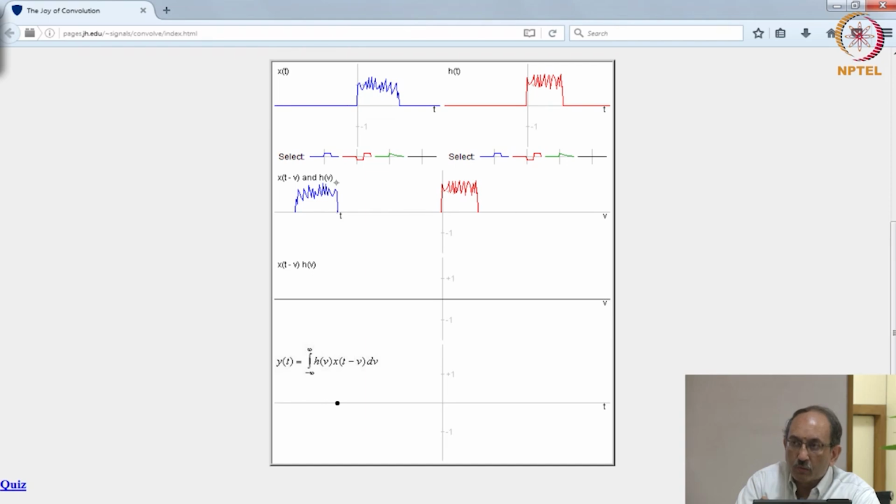So, now what I am going to do is, now I am going to convolve them. If these were two clean pulses, you would expect a triangular shape. Now, let us see what happens here. All right. The final result is still not too different from a triangle because all these variations have been smoothed out. So, this kind of nicely illustrates the fact that when you integrate, all these fluctuations get smoothened out. So, if you have not seen before, you may not have guessed just based on equations.